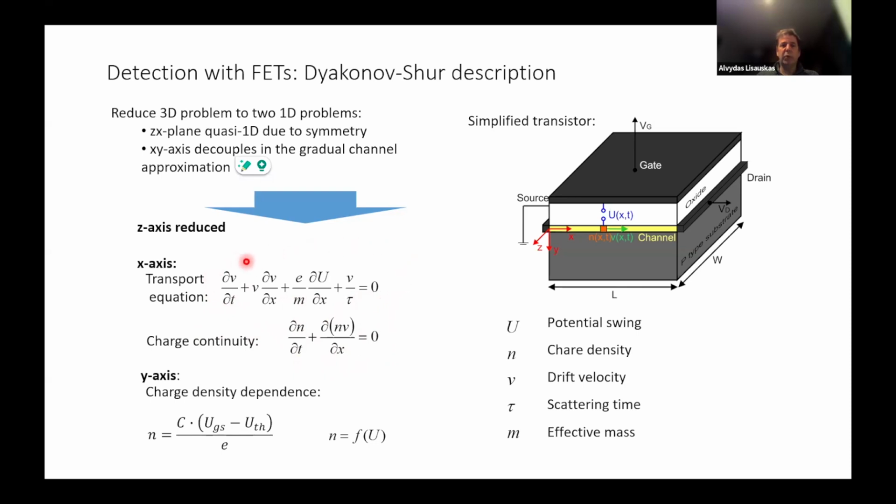One can write the transport equation in very different forms. This is just as originally written by Dyakonov and Shur, in terms of velocity. In electrical engineering, this transport equation is mostly written for a current, which is a product of N and V, but it is absolutely identical as long as it's correctly written. What we don't have here are diffusion terms; they are omitted.